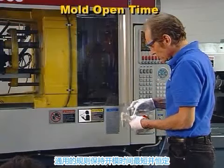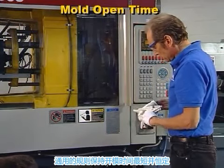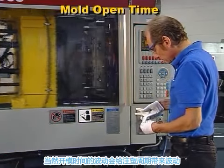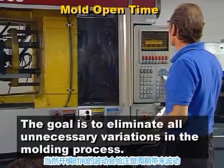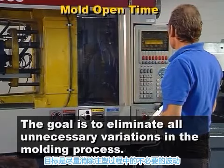The general rule is to minimize the mold open time and keep it consistent. While small variations in the mold open time may have only a small effect on the melt temperature and the mold temperature, the goal is to eliminate all unnecessary variations in the process.